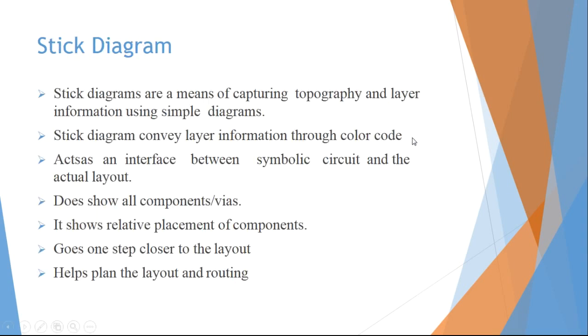So just a little bit about the stick diagram and why it is required for creating a layout. Stick diagrams are a means of capturing the topography and the layer information using a simple diagram. Stick diagrams also convey layer information through the color code, which we have shown in the previous slide.